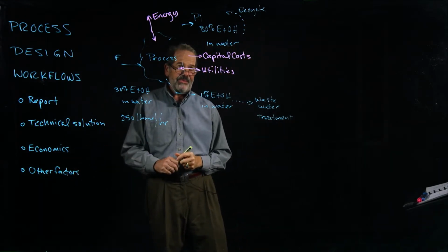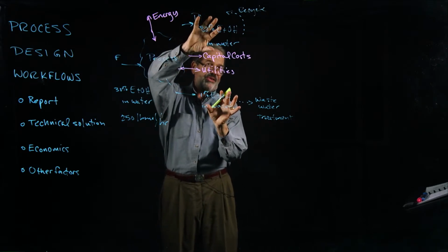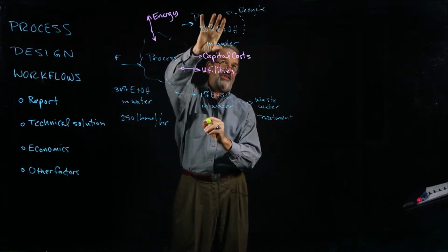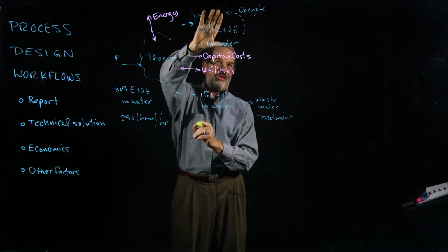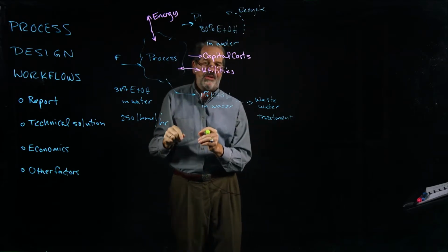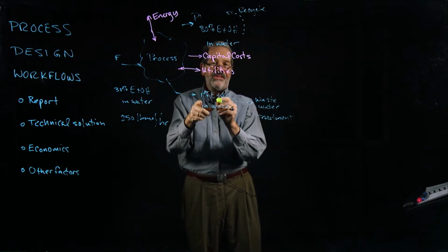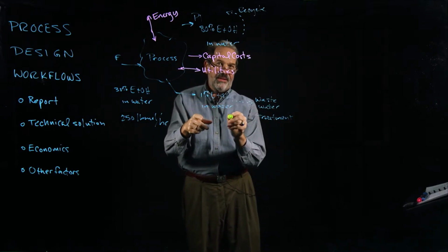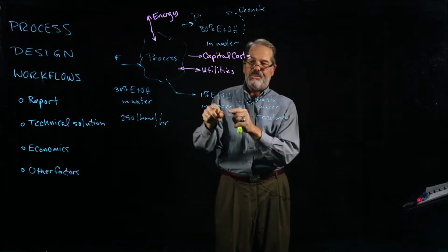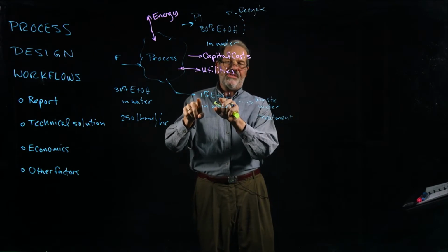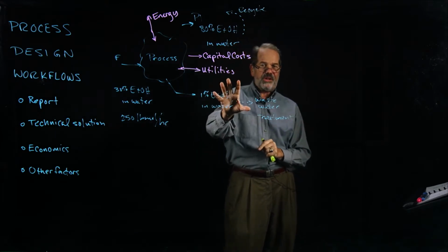That is, we talked about things like regulations. Are there any regulations on these streams? Maybe not so much this one, because this is going back to a process someplace. Its specifications are set by the requirements for recycle. But this one, going to wastewater treatment, is of concern. It's got ethanol in it, and if you send it back to wastewater treatment, you're going to be paying a cost for the degradation of every pound of the ethanol. So that's going to be a question.